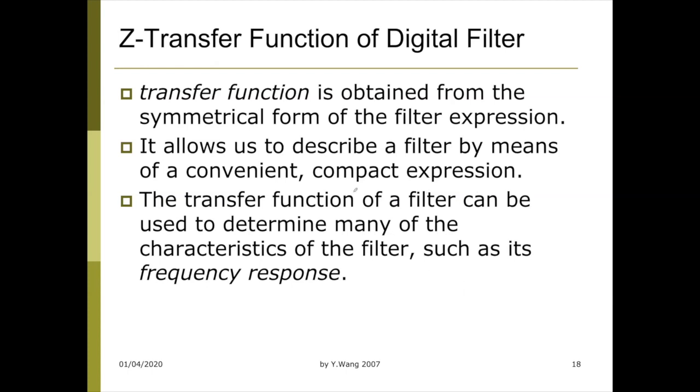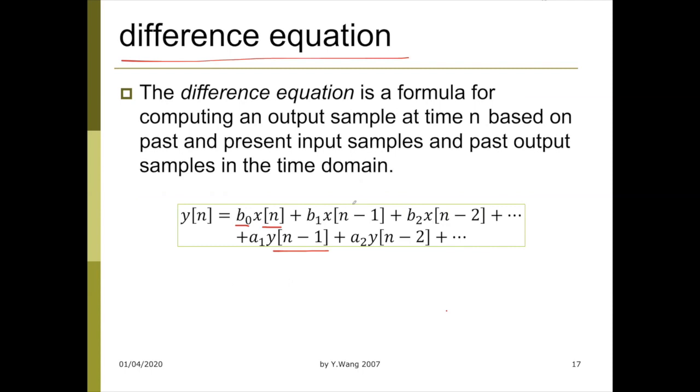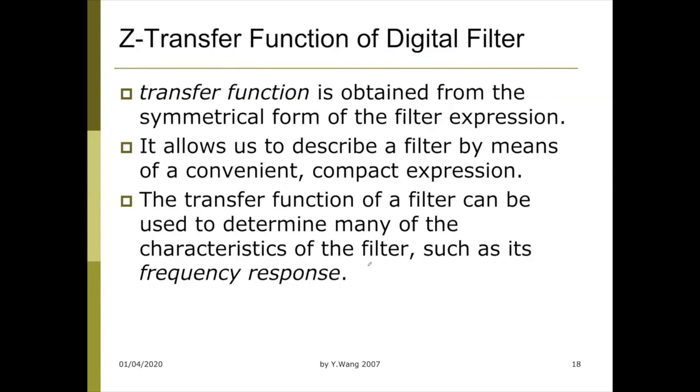Okay, so the Z transform. Why we need the Z transform is because the difference equation we have looked at so far doesn't give you any facility or fundamental tool to explore the frequency domain properties. So we need to use a transfer function, which can get the relationship between input and output, ignoring all the previous terms.